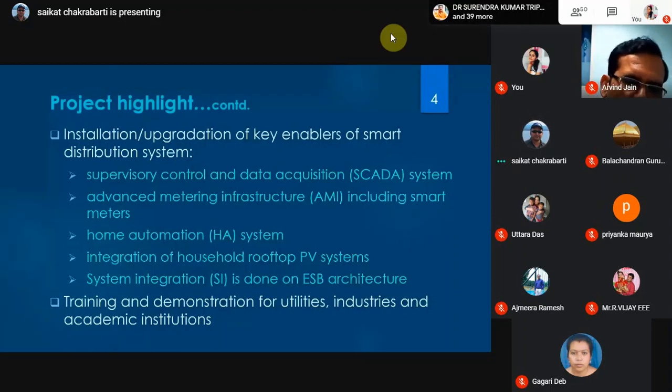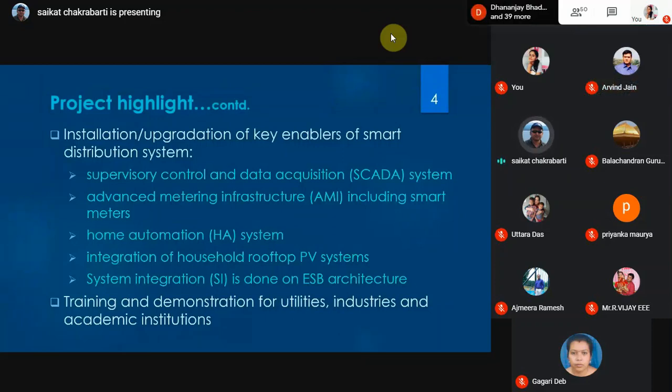Okay, and the entire distribution system is underground. Then from the outgoing of the 415 volt side, we can take the cables out, and we connect it to feeder pillars, and from there it is distributed to individual houses. So in all these substations, we have installed a remote terminal unit. So the entire 11 kV network, including 33 kV and the 415 volt outgoing feeders at the 11 kV substations, are under SCADA now. We can monitor and control the entire distribution system.